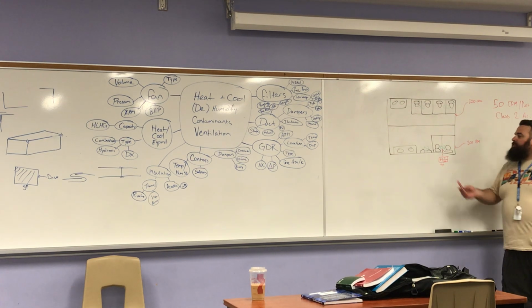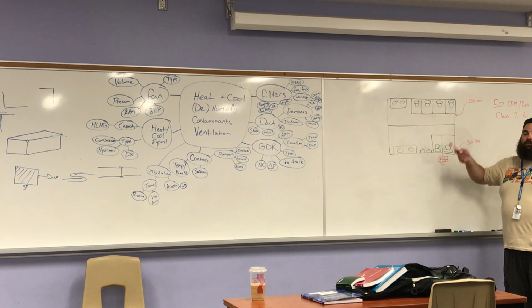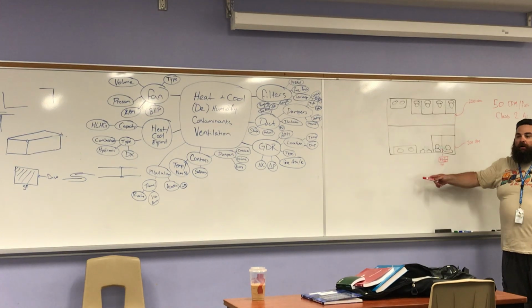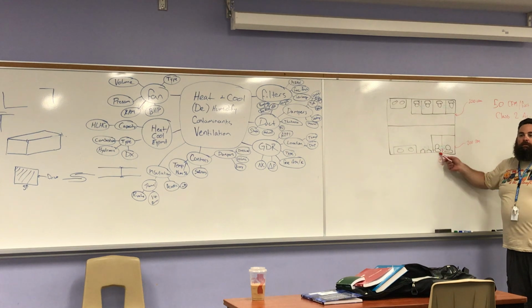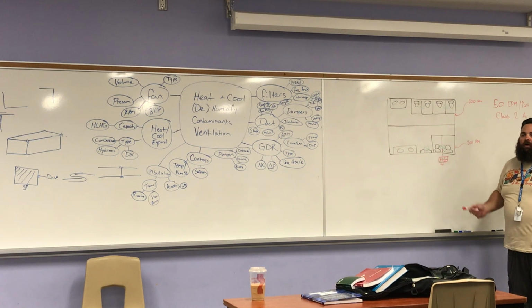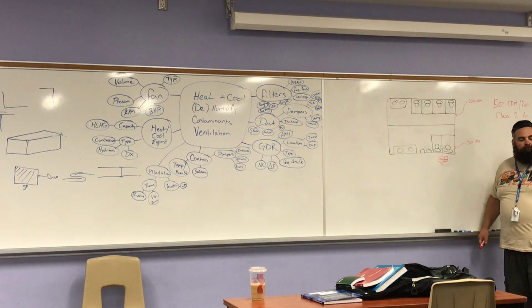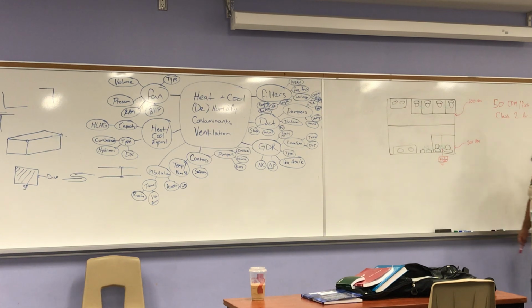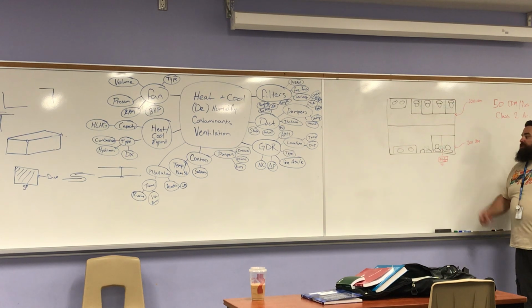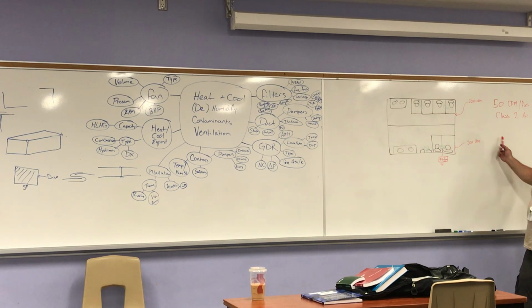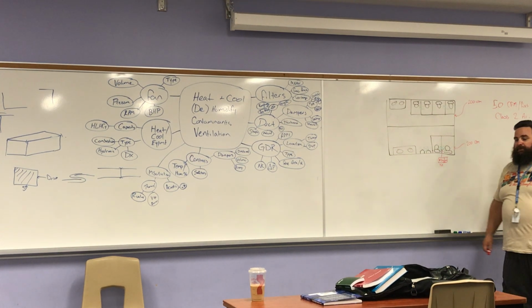Okay? There's no need for me to clog my drawings with a tag everywhere if it's all exactly the same. I've got 4 identical grills here. I can just do that and say typical for all of the bathrooms. Could you also just do a legend instead? Yeah, so I will have a legend or a schedule, but I still have to identify on the drawing which diffuser registers this. Because again, this is part of a whole building. Presumably there's going to be other grills and diffusers.